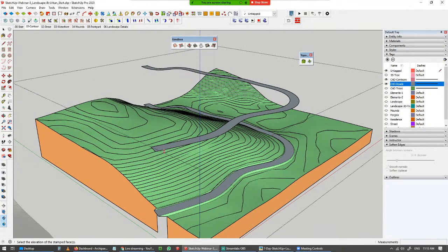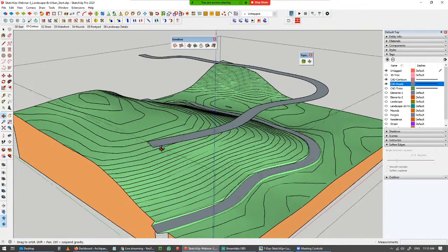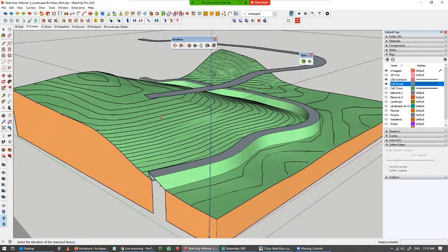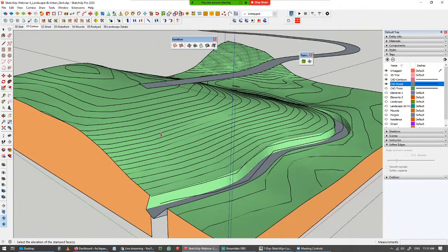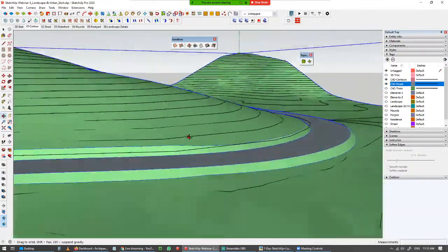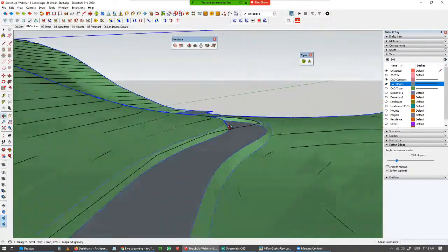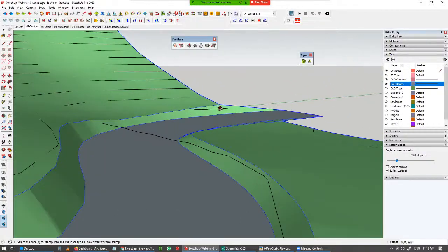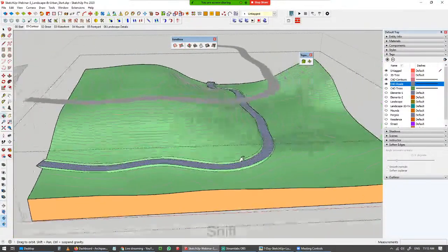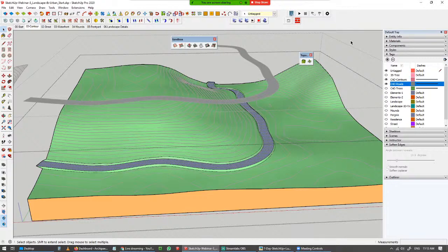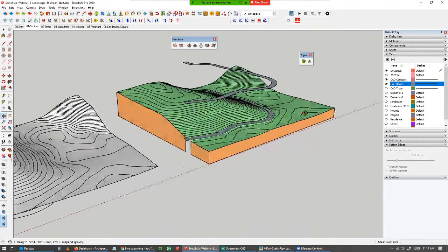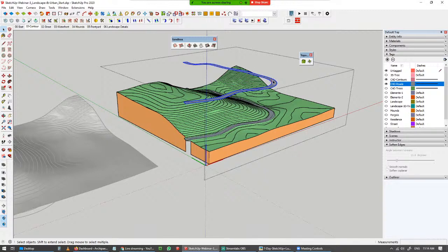Thus we have the road projected on the terrain, and you can see that it also merged it with the terrain. Now we can move our cursor to provide an appropriate level. I think somewhere between these will be fine, and thus we have the road going along the terrain projected on the 3D model like this. Now you can go on adding further detail on this particular face, and I will also show you how you can create more details on roads in our coming exercises. Now the road is projected, we can get rid of these CAD lines.